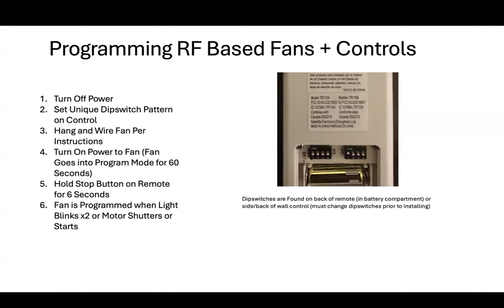Programming RF-based fans. All radio frequency-based controls and fans must be programmed or synced prior to operation. This process creates a unique connection between the control and the fan. Establishing a unique connection using dip switches ensures that your remote only controls your fan, and not your neighbor's or your downstairs fan. Luckily, programming your Minka Aire fan is easy.